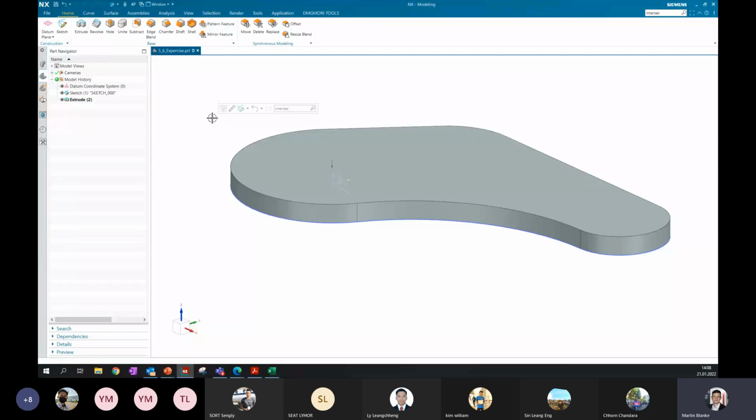The better way, and the way I recommend to you, is to create 3 additional sketches. This has the advantage that if there is any change to one hole, you only have to delete this sketch and the extrude command. I will come back to this point a little bit later.